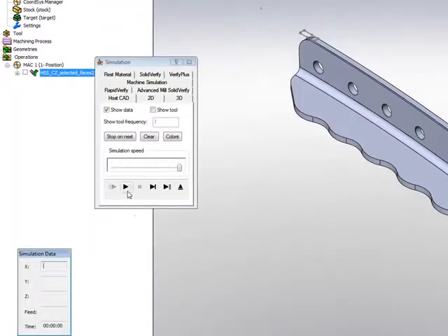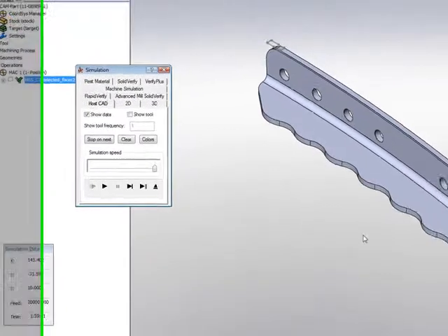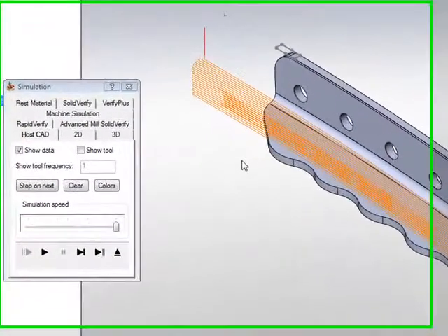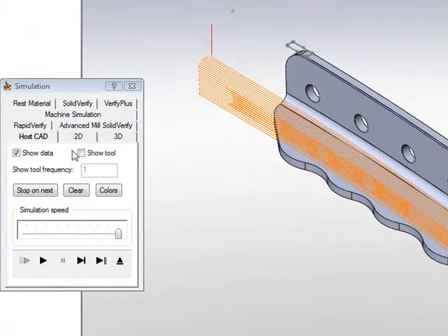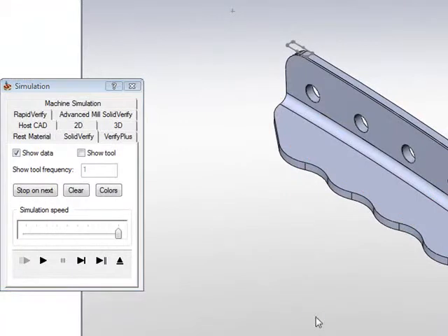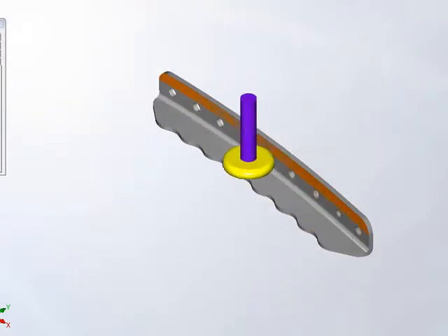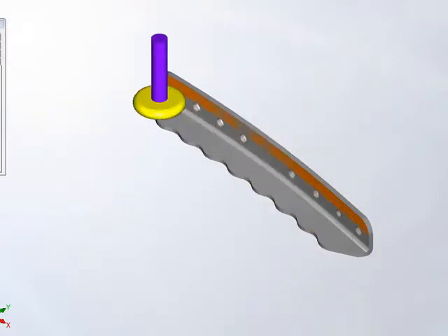And you'll note that my toolpath is being created exactly along the part itself, going directly over those faces as well. I'll use also now my solid verify option in my simulation. You can see that my tool is actually working directly on that wall, machining the entire wall up until the end.